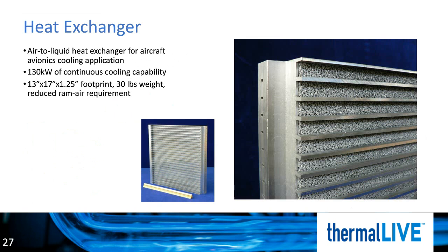With liquid-cooled systems, you not only need to draw heat out at the heat source, which is typically an electronic component, but also need to reject that heat to the environment, typically with some kind of air-to-liquid heat exchanger. Shown here on this slide is a compact ram air-to-liquid heat exchanger for an aircraft avionics cooling application.